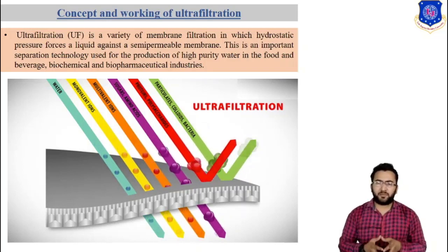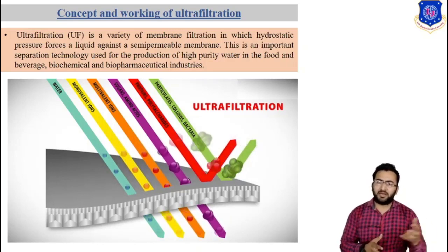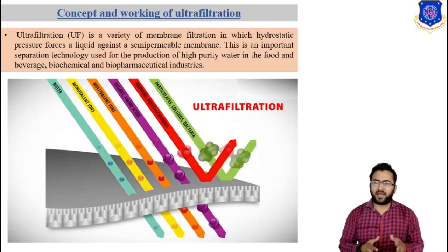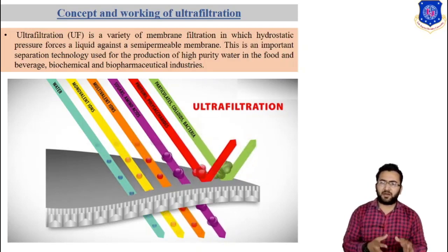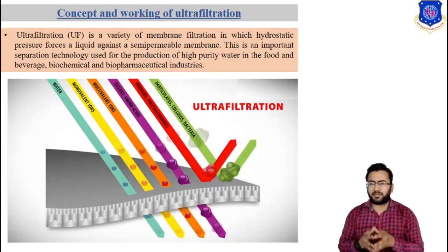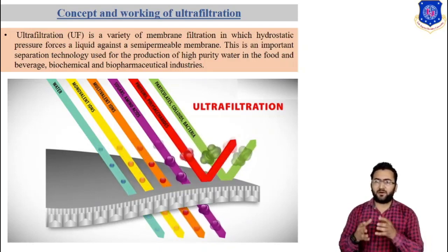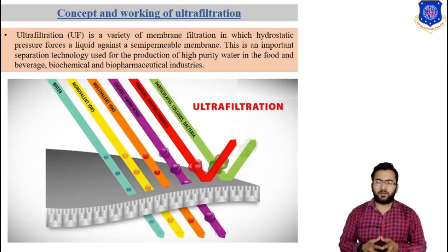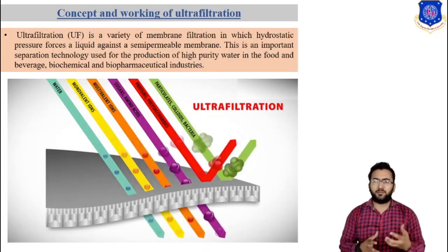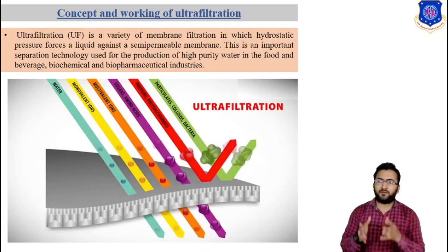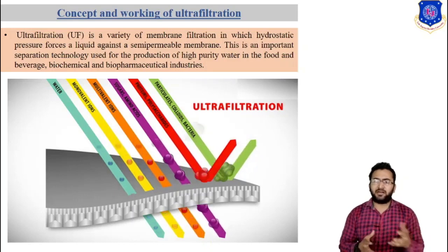Generally, ultrafiltration membranes are available in four basic modules. These are tubular, hollow fiber or capillary, flat sheet and ceramic. Commercial diameters of tubes are 5 to 25 millimeter. Tube configurations are characterized by the least susceptibility to plugging, small replacement area and ease of cleaning. Fibers range from a few millimeters down to 250 micrometer. The advantage of the hollow fiber configuration is a large membrane area per unit volume and the possibility of operating with back pressure for flushing the module. Flat sheet membranes are most commonly made into spiral wound modules and plate and frame devices.